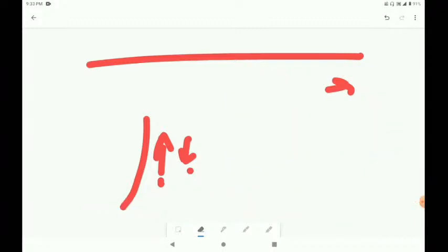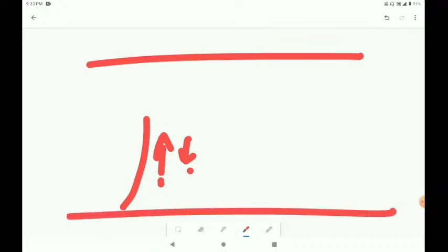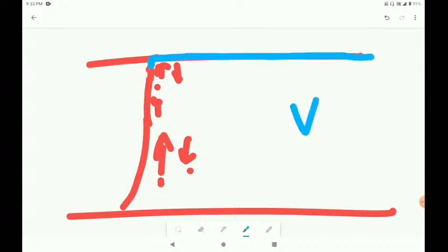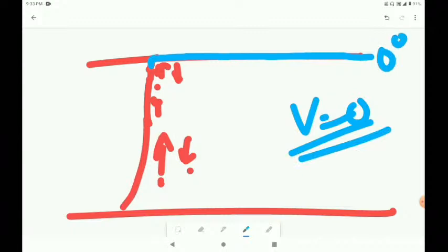What happens is, as this keeps on decreasing, at a point both of these vectors are equal, and at this point it becomes 0 and there is no change in position, which means the angular velocity is 0 at the set point. So with this we are completed with the PD loop of the PID loop, and this is as simple to understand.